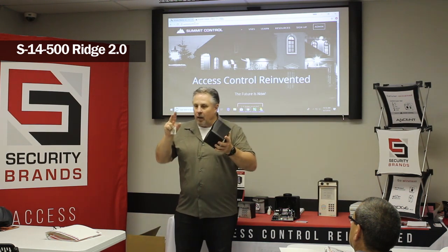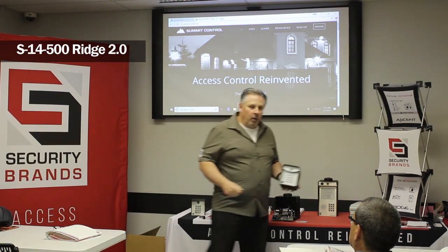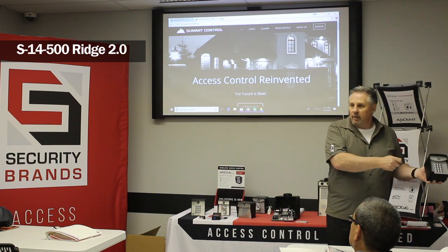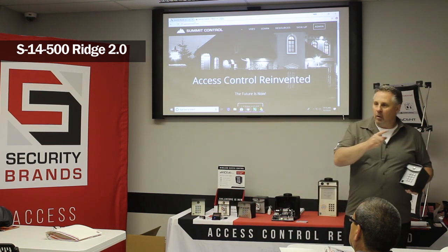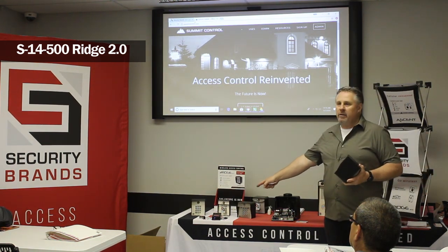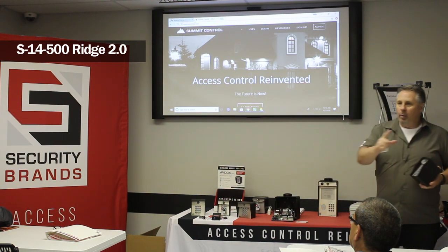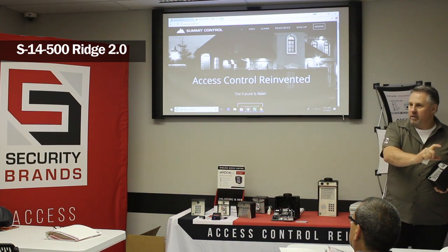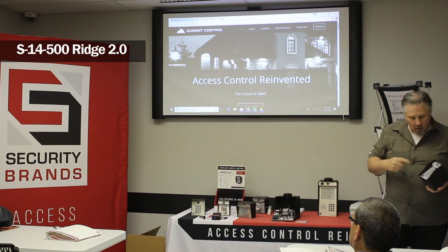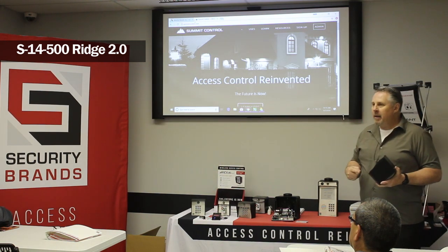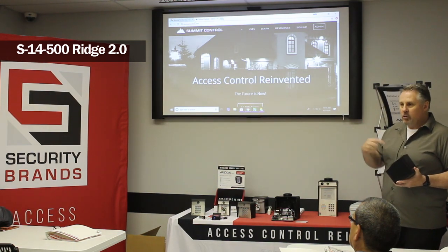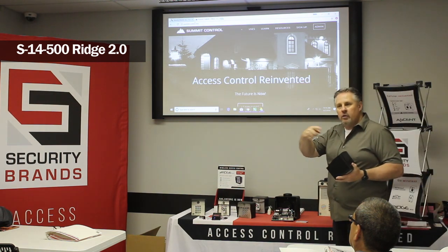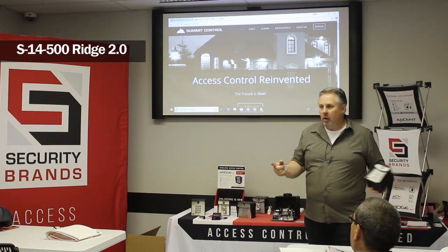Let's say you have not only a vehicle gate, but over here on the residence you have a pedestrian gate. So you go to that device, you put in a second receiver. You press the pair button at that receiver, boom, that light's blinking. 1251 9 star 2. Star 1 for frequency A, star 2 for frequency B, and you're paired up.